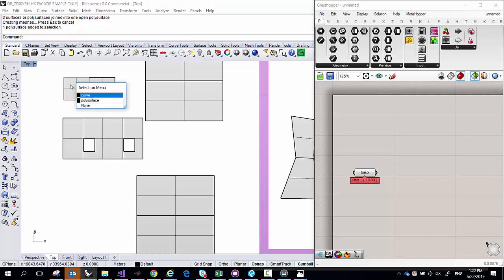Draw a rectangle. You have a rectangle? This guy. Yes. Okay, so just copy, grab this guy. He's a surface actually. Right click top here. No, with right click, not left click. Right click and then go shaded. Oh, okay. But that's a surface, right? We were talking about drawing a rectangle curve. So that should be polysurface. Polysurface. Okay.